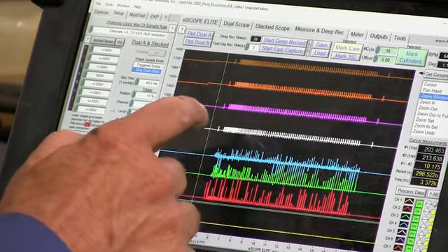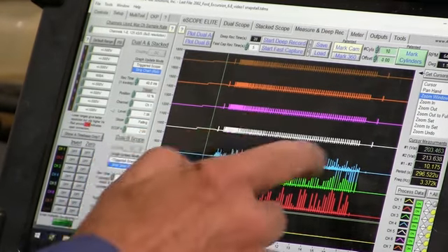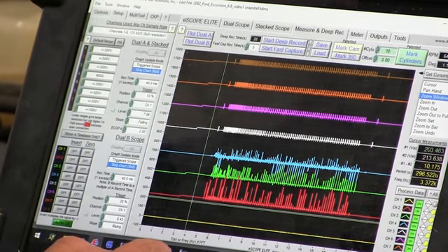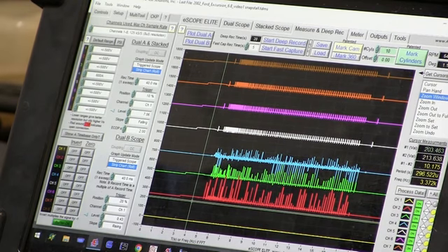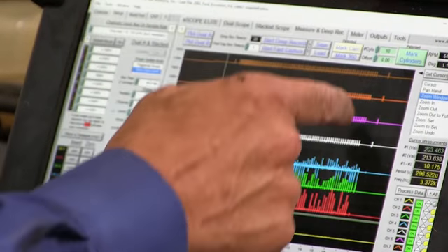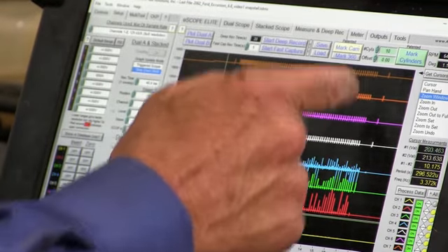But when the engine's not going down the road, because he figured this strategy is when it's going down the road and it's under power and he sees a differential between the output speed sensor of the tranny signal and the input signal, and then the tranny's slipping. So as soon as he sees the tranny slip, he's going to shut these injectors off.